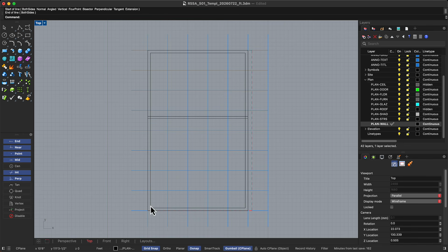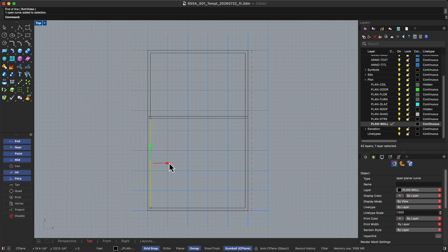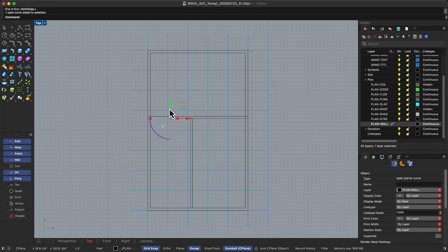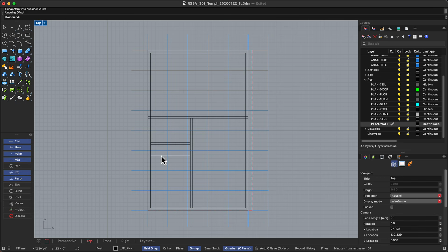Next, reserve approximately 10 feet or 3 meters for the bathroom and office zone. This is the minimum width we want to maintain for a comfortable room. Within this service zone, allow approximately 6 feet or 1.8 meters for the bathroom. Add another horizontal partition to define the laundry and water heater area, allowing approximately 2 feet 8 inches or 0.8 meters of depth.